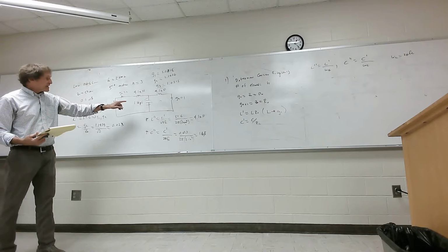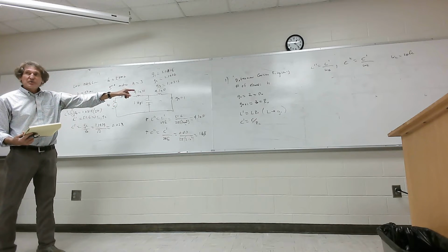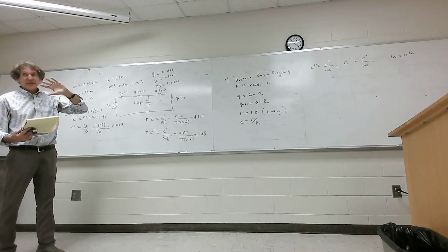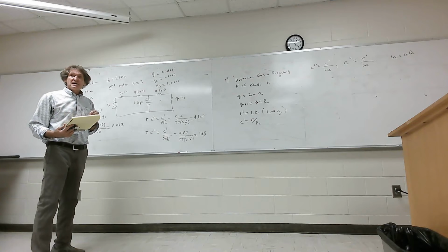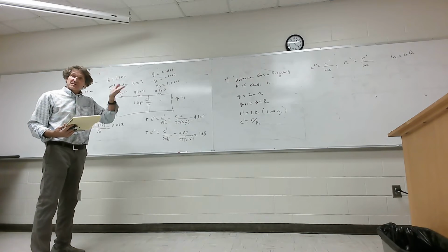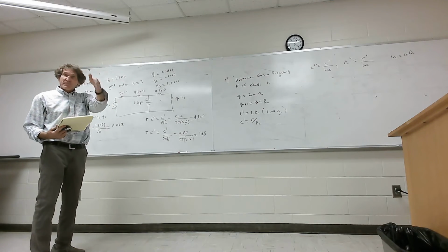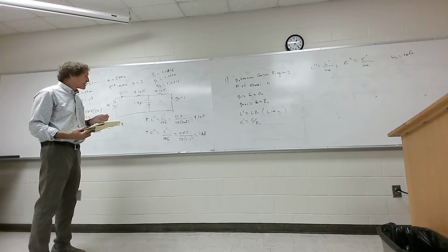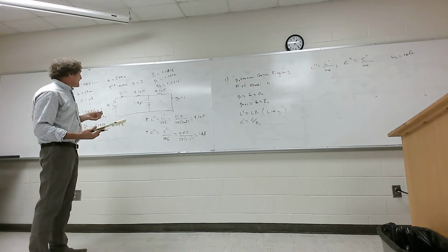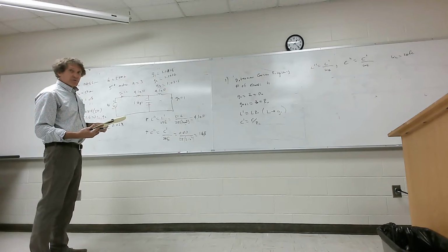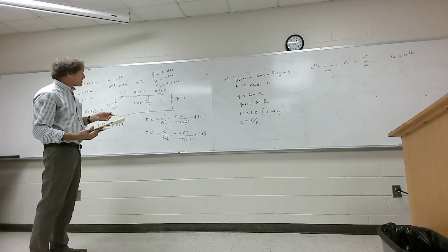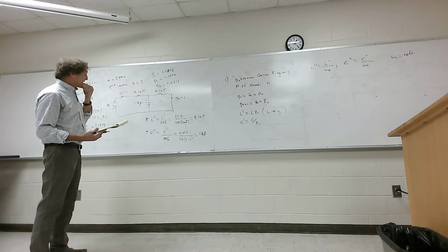Well, for each one of these elements that you add, you're going to get a roll-off that goes up by 20 dB. Typically, not every single time, but this is probably going to have 60 dB of roll-off. That means it's going to come down very quickly, or go up very quickly, depending if it's low pass or high pass. This right here is a low pass filter, so basically the high frequency stuff's going to get killed very quickly. And where it starts going down is at 2 gigahertz.